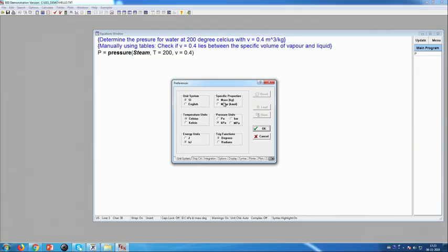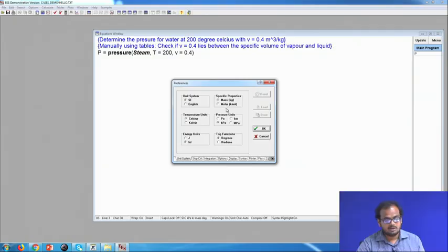See, specific volume is the total volume divided by the total mass. So, you can also have specific molar volume, which is the total volume divided by total number of moles. However, if you select that, then only it becomes on a molar basis, but now we are working in a mass basis, because that is what we have followed in the theory class. The temperature units, it is in Celsius. This is the very important step. Okay. Ideal gas equations and all this work in Kelvin, but typically for engineering one works with Celsius.